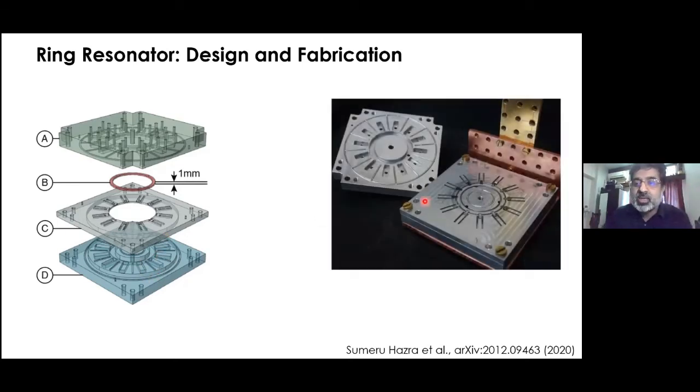Here again, you see how the 3 parts look. Here's the bottom part and the middle part, which contains these resonators, and then you place the chip, and then you close it up to make the full system. It's nice, compact, modular, and nicely sealed to protect it from radiation and noise. You can maybe barely see these little holes on the top. That's where the measurement and control signals come in. You put coaxial connectors on them, and that's where the signal comes in and out. So it also has a nice 3D integration, so you don't have wires crossing each other.